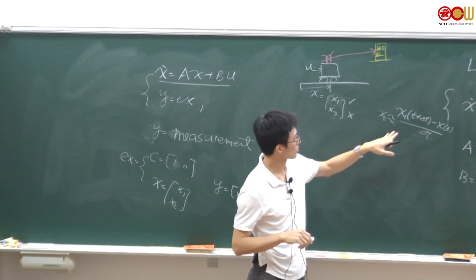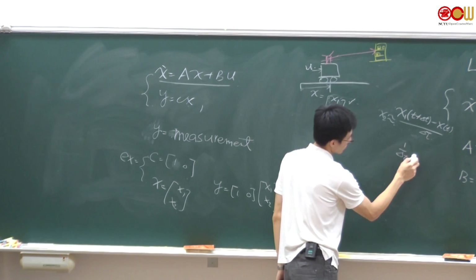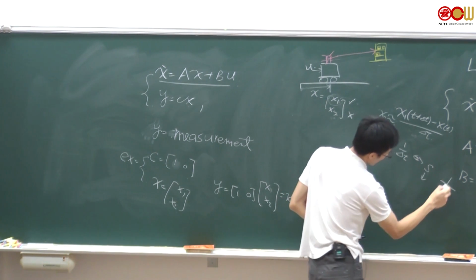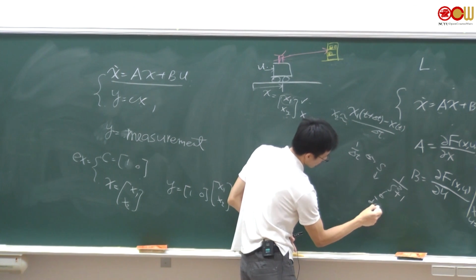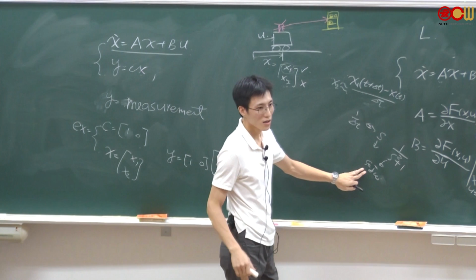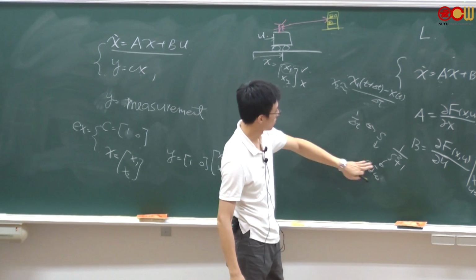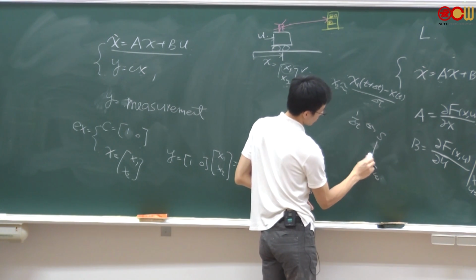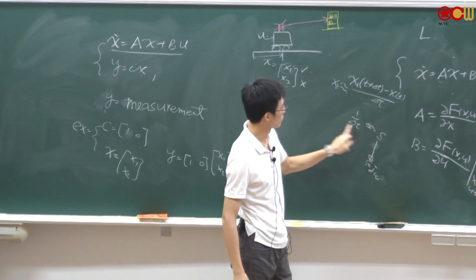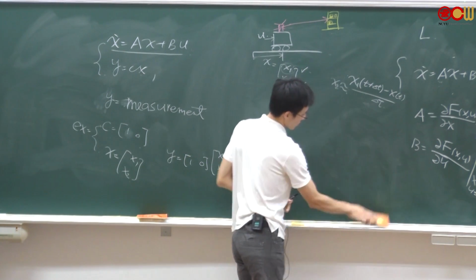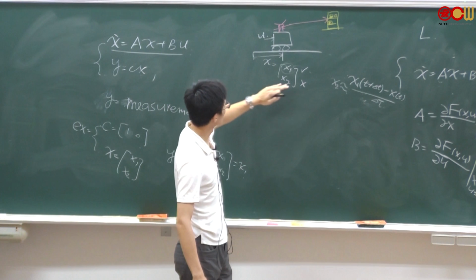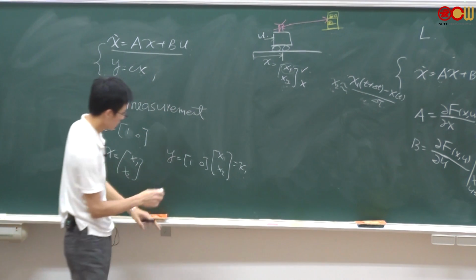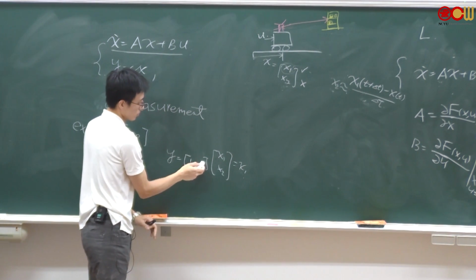OK, differentiation is very sensitive to high frequency content. Differentiation is similar to, in a Laplace system, putting in an s, where s is equal to j omega, right? So omega is the frequency. When you have high frequency content, you plug it in and the result becomes very large. So it is very sensitive to high frequency content. So anyway, it's very sensitive to noise, okay, using this numerical method. So we don't recommend that you use this approach to estimate x2 given x1, okay. So in this system, the measurable term is x1, not x2. So that's why you put 1, 0 here. Okay.